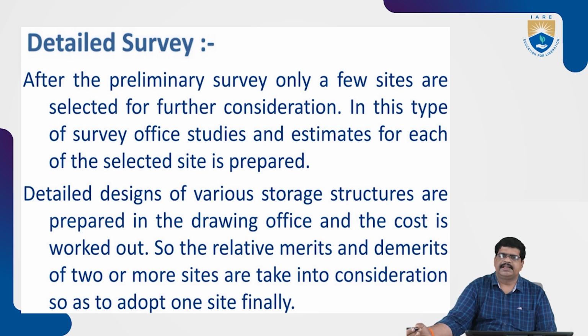The estimation will be taken at 2 to 3 places. Very important is the foundation area, especially the load bearing capacity of the soil in the geological survey. For a better foundation, the soil condition of the particular area matters, and also, as I told, the water tightness. These are all very important factors. Maximum of them will not all be satisfied, but we will consider them among the 1, 2, 3 places.